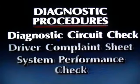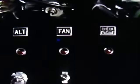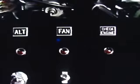Before starting with Step 1, the diagnostic circuit check, you first need to make sure the check engine light works. We'll demonstrate this procedure on our test engine. Turning on the ignition switch, but not starting the engine, should cause the check engine light to go on. If it doesn't, stop right there, because you can't check the diagnostic circuits without the light. To solve an engine light problem, consult your various manuals for complete instructions. Assuming the check engine light does work, you can now begin the diagnostic circuit check.